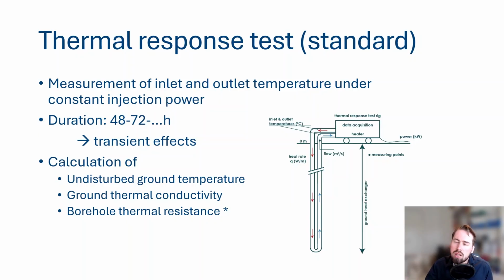Now there is a star next to that because you need to be aware that the way you design your borefield, for example with antifreeze and a certain mass flow rate, may not be the same as the regime or the flow conditions at which the measurements take place. Because these thermal response rigs have their own pump, so they have their own pressure drop, pump characteristics and flow rate, etc. And also, typically these tests are not done with antifreeze.